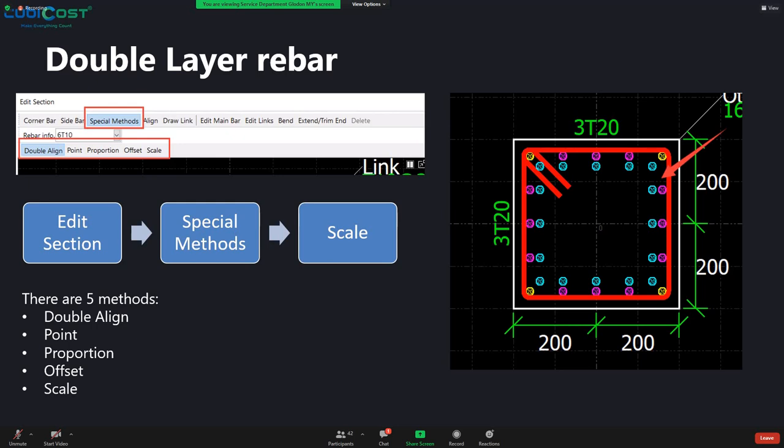Basically, you need to do such adjustment in edit session. In your edit session, select special method. Under special method, we have 5 types, and you can utilize those 5 options, one of which is to border out this double layer rebar. But I strongly suggest you all use scale, because scale is the most efficient and most straightforward method to capture this double layer rebar.